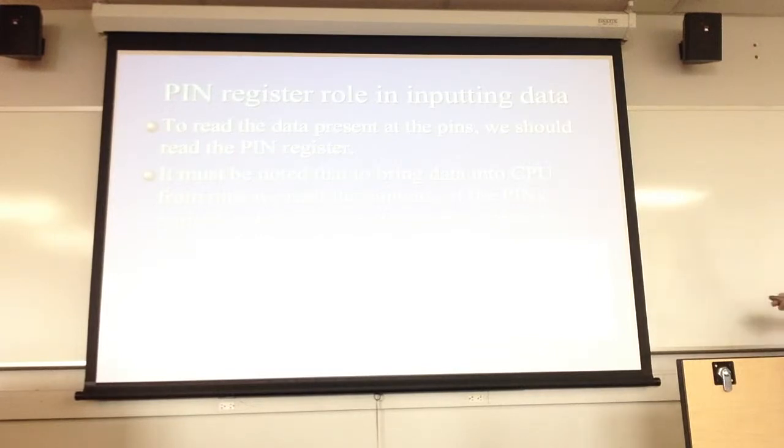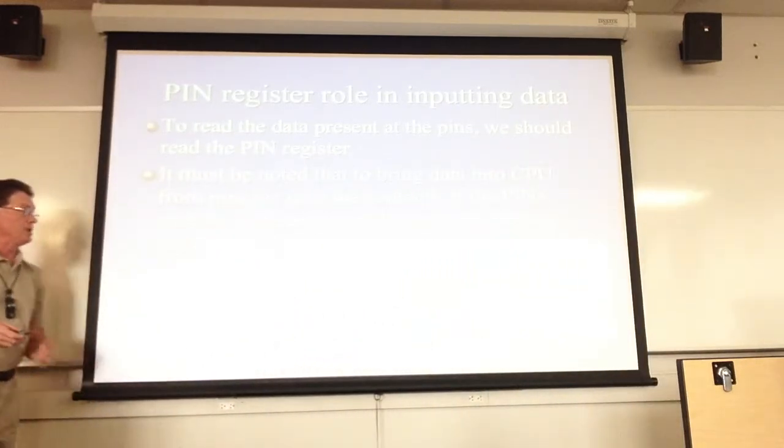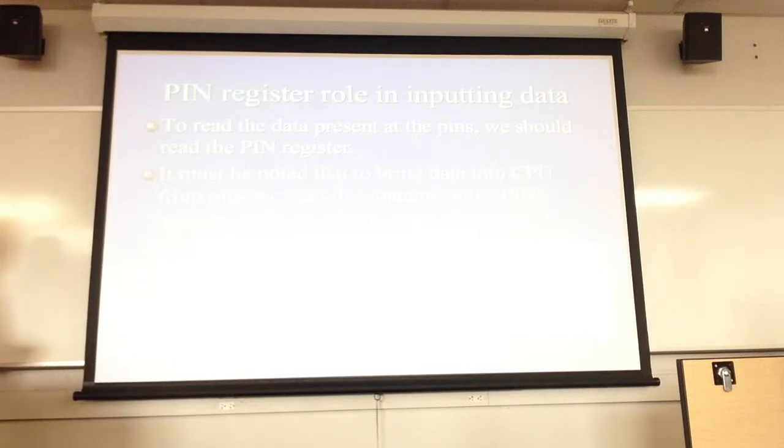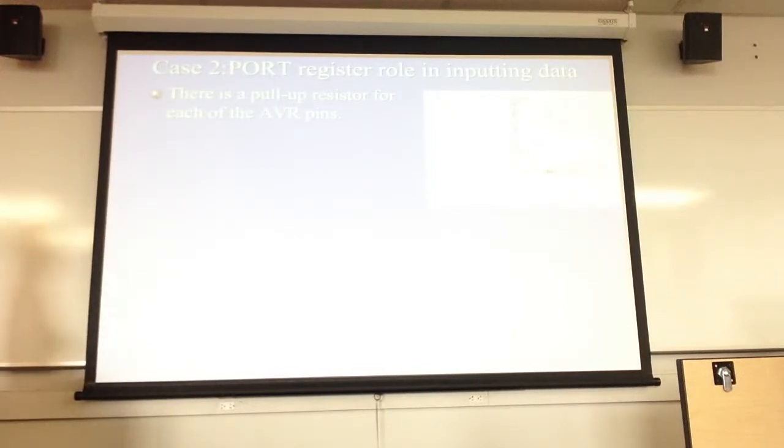Be aware that this is just about done. It must be noted that to bring data into the CPU, we read the contents of the PIN X register. When we send data out, we're using the PORT X register, okay? All right, here's what's going on when I'm going to input some data in there.